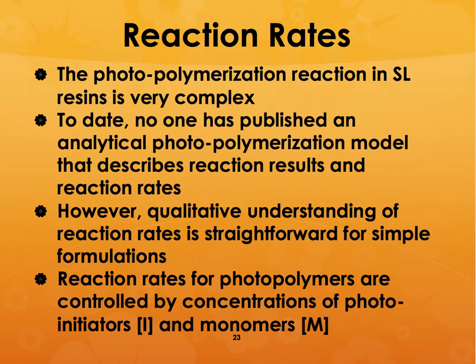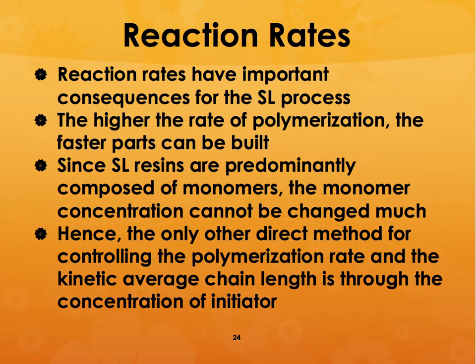Now, how quickly can you make these things react? It's a pretty complex question. There are hardly any analytical photopolymerization models that describe the reaction results and reaction rates. There is some qualitative understanding, but most of the time they are pretty complex. The reaction rate by itself has a very important consequence for the stereolithography process, because the higher the rate of polymerization, the faster you can build the parts.